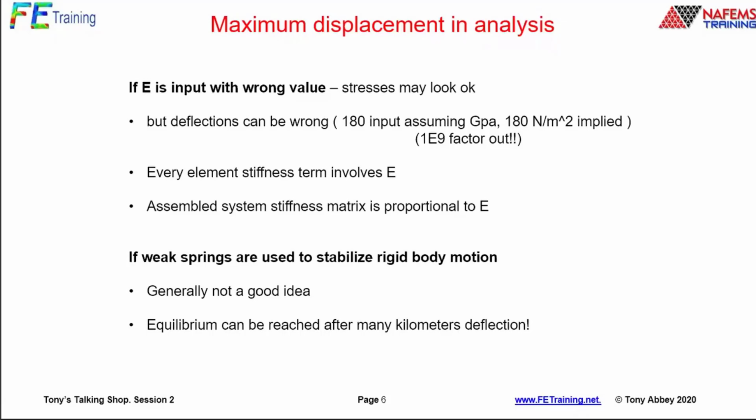It's basically where we're getting close to rigid body motions, or we have rigid body motions. The solver detects that, and rather than giving a hard diagnostic saying, tough luck, I can't solve this because we've got rigid body motions in here, you need to go and do some kind of debugging, it says, don't worry, I'll hand-hold, fix it up for you, and put these system springs in, distributed throughout. It's doing it automatically, so you don't know where they are. And then we can reach equilibrium because we've got these springs in.